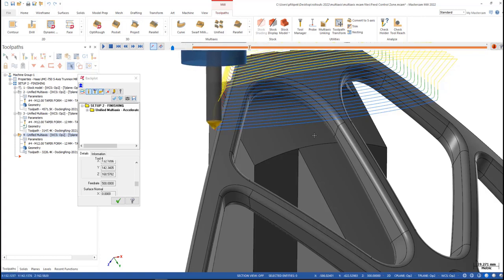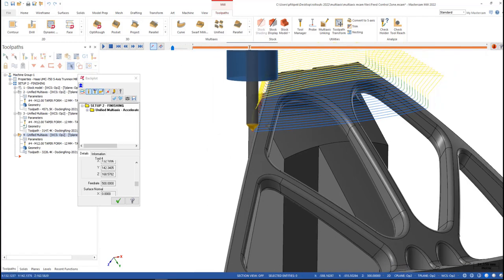As you can tell, this is really going to speed up your time. You do the cut that actually means something, and speed up through these zones where it doesn't really matter, and pick up the cycle time. Also this cut is going to be a nice fluid motion. You wouldn't have to cut it this way. We could come along these, but then you have a bunch of interrupted transition moves. So sometimes this is better, and now it's really better because we can speed up on the zones that we don't want. So it's a great enhancement.